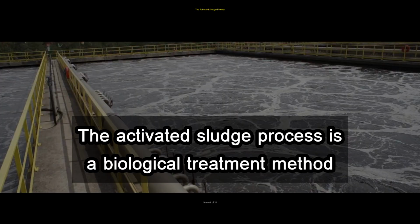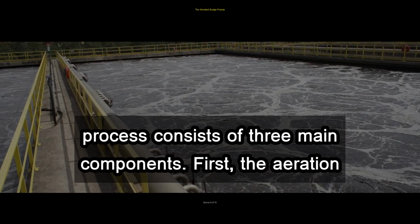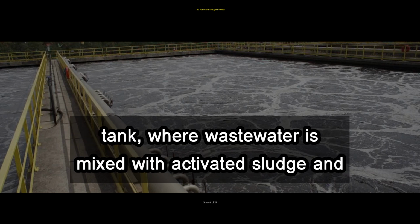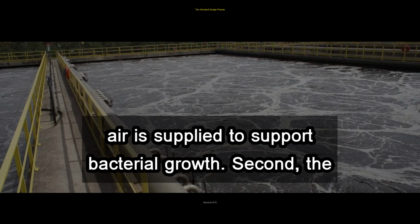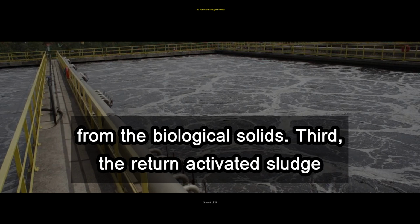The activated sludge process is a biological treatment method that uses microorganisms to break down organic pollutants. The process consists of 3 main components. First, the aeration tank, where wastewater is mixed with activated sludge and air is supplied to support bacterial growth. Second, the secondary clarifier or settling tank, where treated water separates from the biological solids.